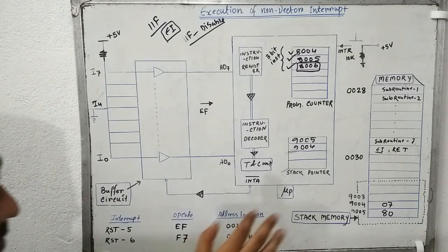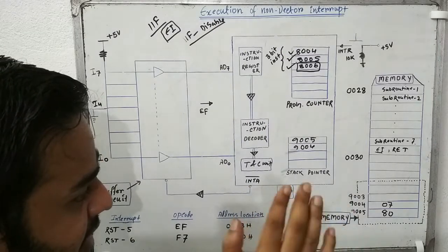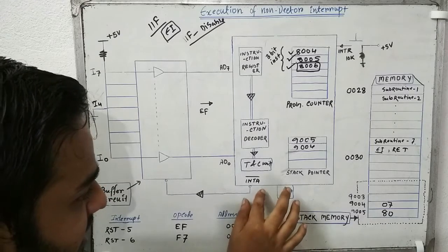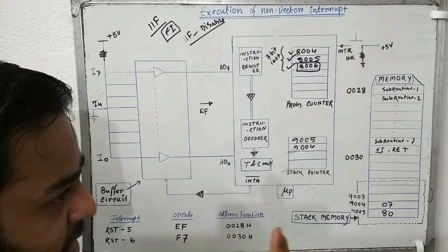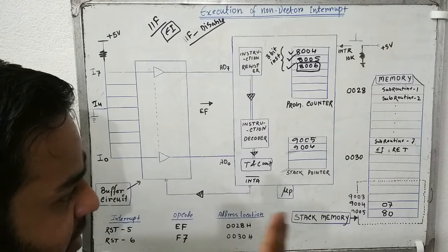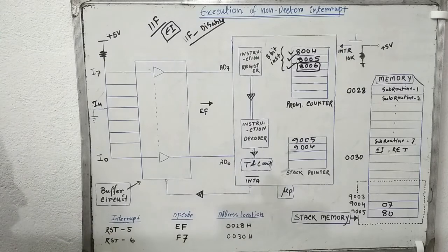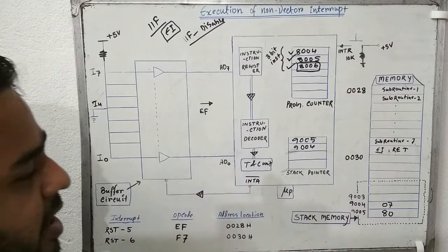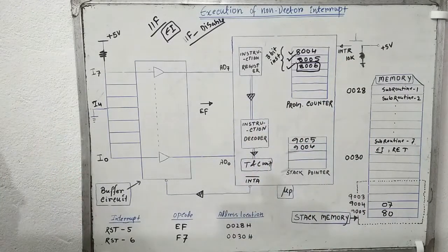And the fourth thing: the microprocessor also sends a message to the externally connected input output device through the INTR pin, saying that the microprocessor will not be able to accept any kind of interrupt request for the time being. This fourth thing happens consecutively when the microprocessor accepts an interrupt request from the outside through this hardware interrupt pin. So now what will happen?